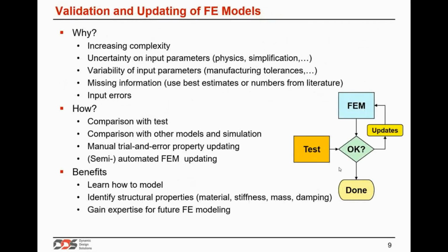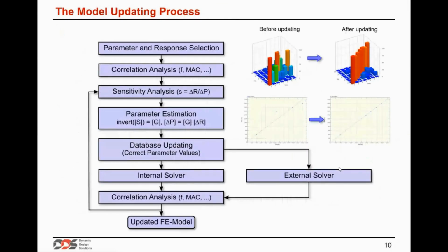So this validation and updating can be done by comparison with tests, and also with other, more refined models, reference models. Updating can be done using trial and error, but of course it's much more efficient to do this in an automated way. The benefit is that it is part of a learning curve to learn how to develop models for a specific purpose, how to estimate the input parameters, and in brief, gain expertise for future modeling.